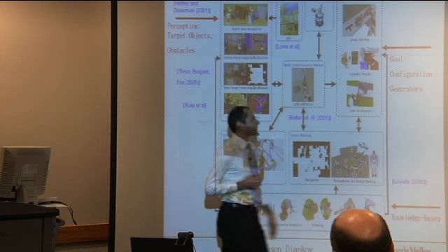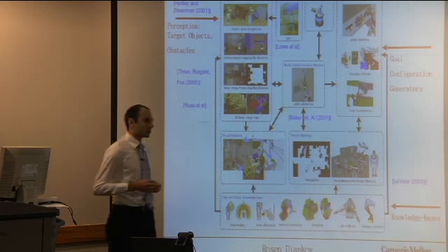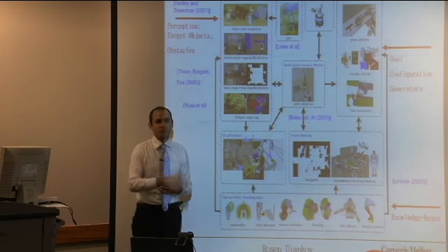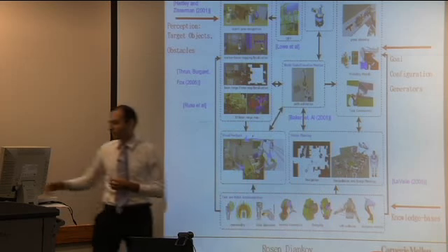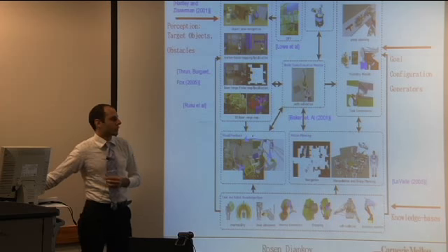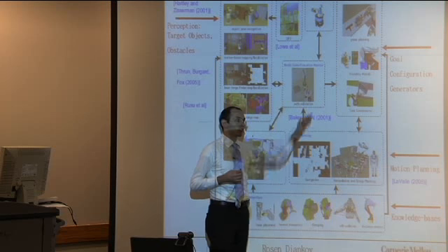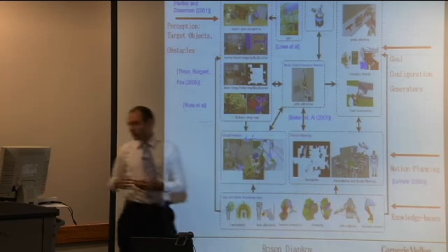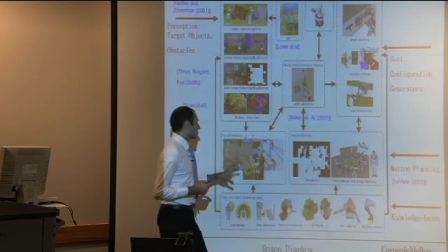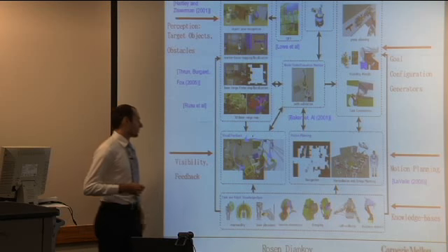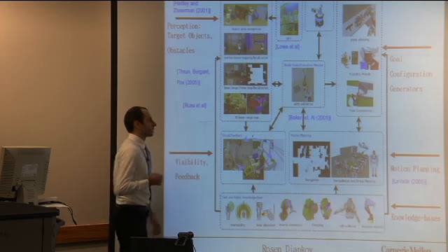Finally, we make a very big deal about the importance of goal configuration generators in the task. The task specification itself has some very high-level goals, for example, pick this object and place it here. And the goal configuration generators convert that into explicit goals that the robot can move to. Then the motion planning combines the goal configuration generators with the current state of the robot. There is an execution monitor that always monitors the state of the task, and there's also a visibility and feedback phase that takes the camera sensors into consideration when doing all this.